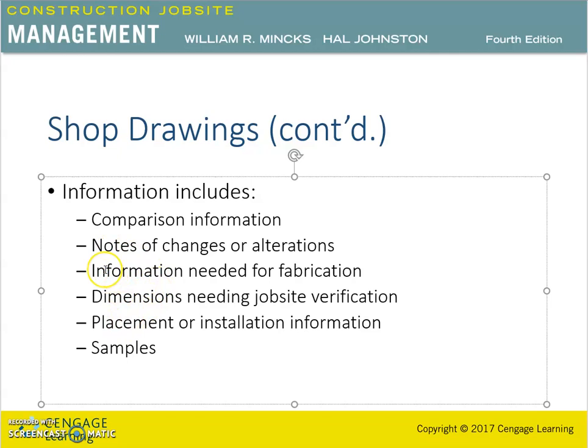The information needed for fabrication: information needed to fabricate the product, dimensions, manufacturing conventions, and special fabrication instructions should be included on the shop drawings. It should be clear to fabrication personnel what will be manufactured from the shop drawings alone.